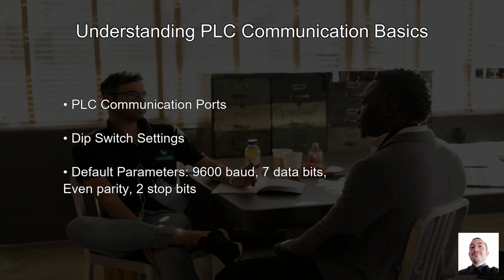Now, let's dive into the fundamental principles of PLC communication. Picture this: your PLC is like a central command center, communicating with various devices and systems. The key to successful communication lies in understanding the ports and settings. For instance, the peripheral port on an Omron PLC requires specific dip switch configurations. Setting dip switch 4 to off and dip switch 5 to on ensures the peripheral port uses default settings, crucial